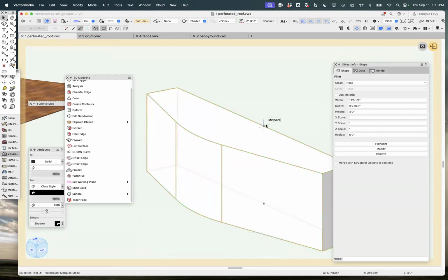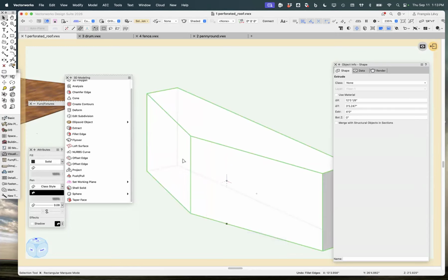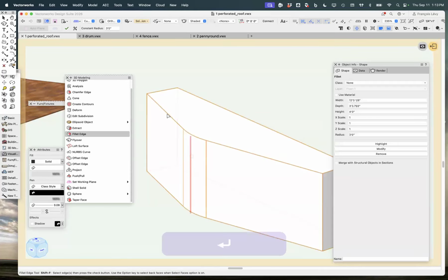Before you have the fillet, it was just 2 surfaces. And so the fillet is just this edge between these 2 angled planes. So when I click on that and hit return, then it makes a radius. It makes a fillet. All right, I see. Thank you. And then I play with that radius until I get one that I'm happy with.